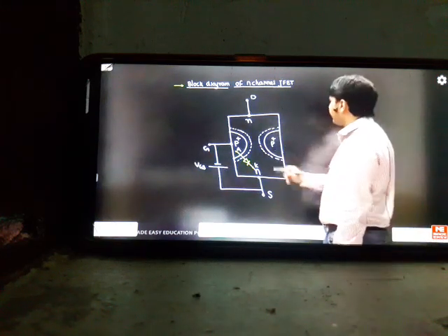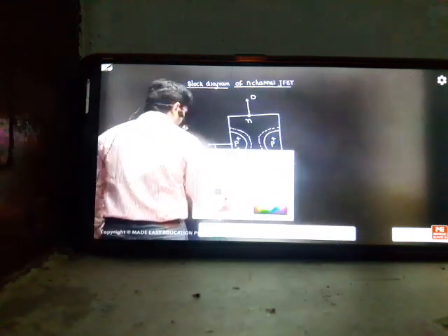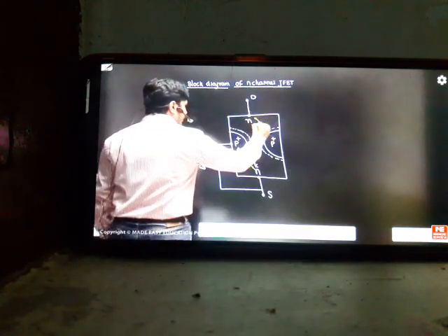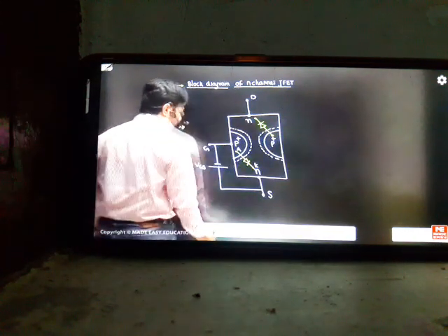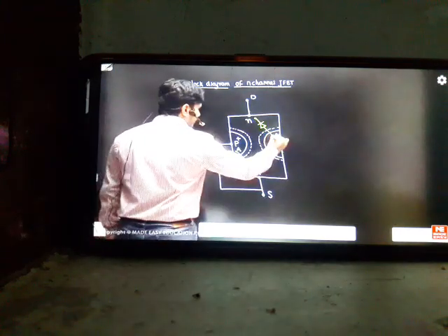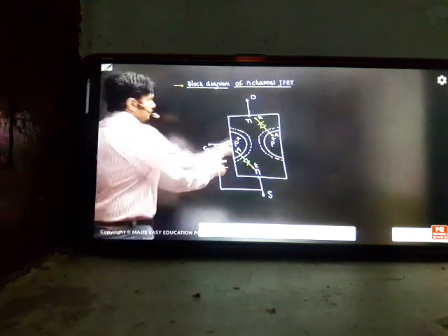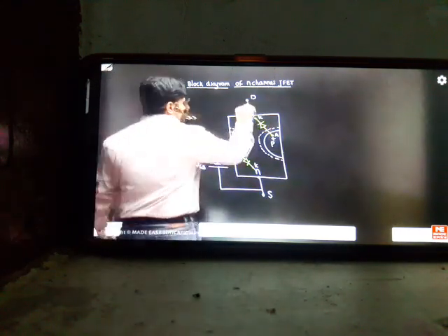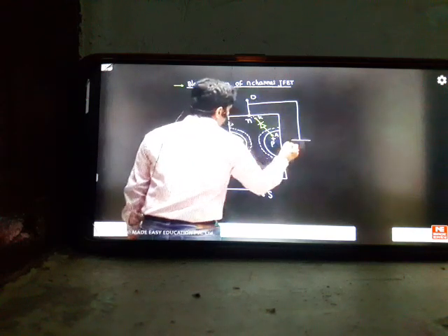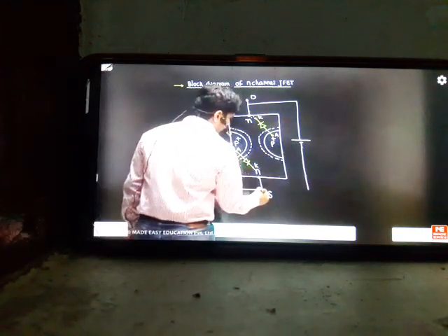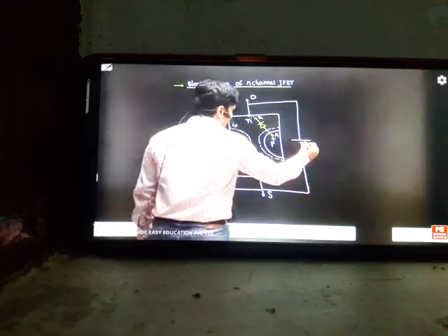And the same thing, the drain should be reverse biased. What is the drain concept here? Take one diode again, from here to here. Always take diode representations to understand the concepts better. Take this as the anode and this as the cathode. You want to make the cathode reverse biased. Therefore, the drain has to be positive. Then the diode will become reverse biased. So this is the simple way of understanding JFET devices. This is called your VDS.